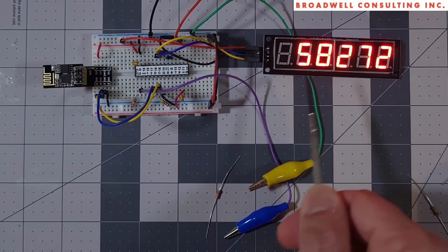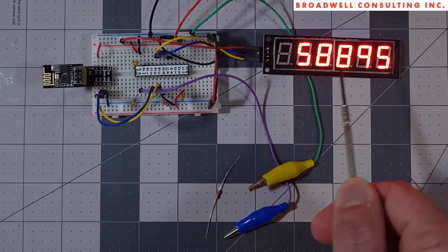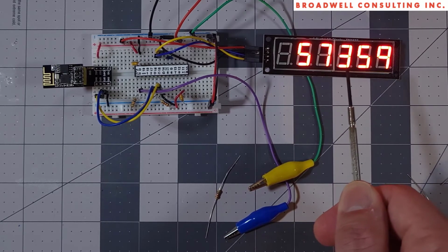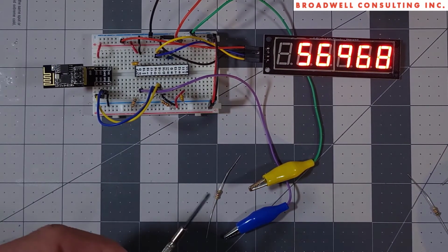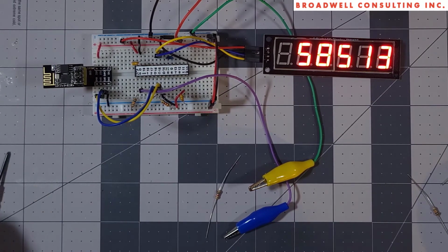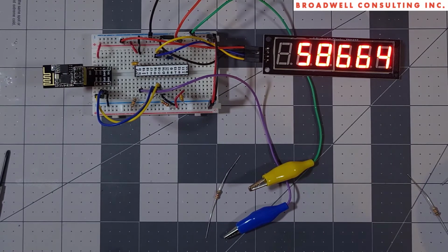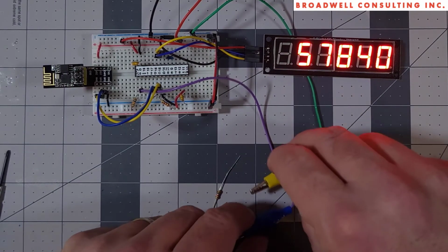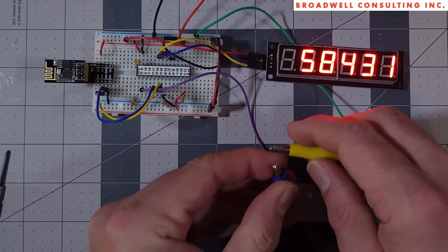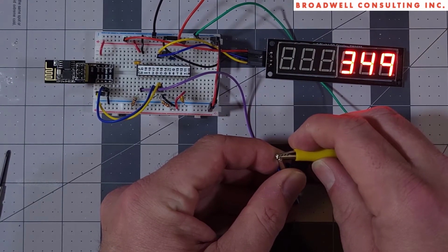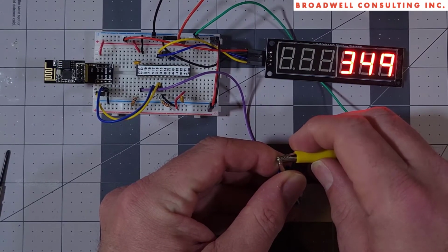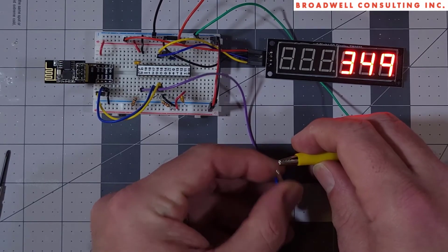You can see that the sketch is showing the resistance measured on the display, and that right now we're getting about 60 kiloohms, which is the top of the range for this particular measurement. So if we short these 2 guys together, that should be 0 ohms, but we see we've got an offset of about 300 ohms, and we'll see that across all of our measurements.